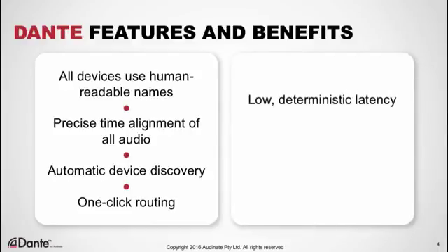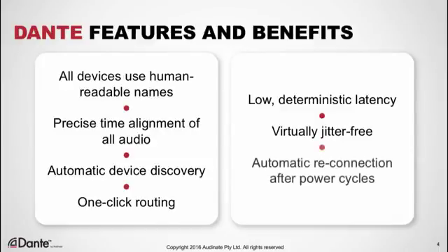Dante also offers low, 100% deterministic latency and a clocking scheme that eliminates sources of jitter and clock propagation problems. And finally, Dante offers automatic reconnection of all devices and channels after a power cycle or teardown and setup cycle.